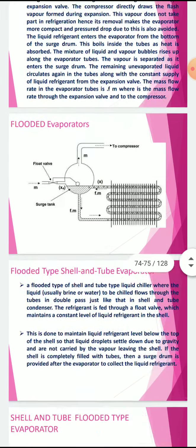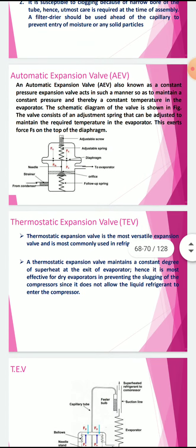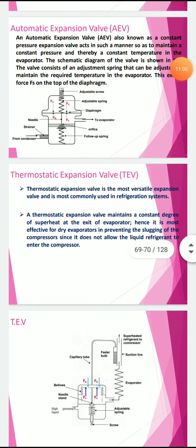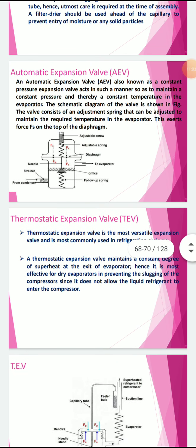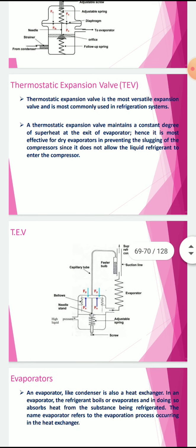And we are left with the devices in evaporator. Of course, the thermostatic expansion valve functions like a most suitable expansion device, because it avoids the liquid refrigerant to enter into compressor.